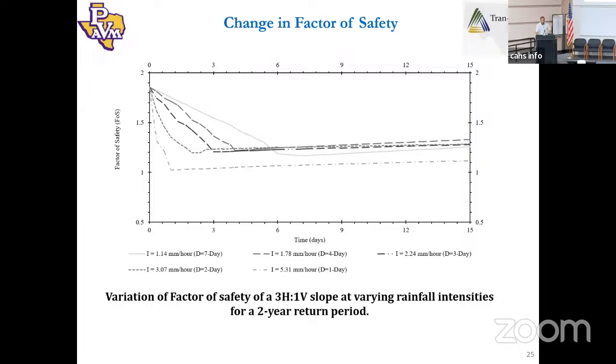But sometimes we have to make a steeper slope, and TxDOT is kind of forced to make steeper slopes to accommodate more frontage lanes, because based on the traffic study, they found that for this particular section, a lot of traffic has been added. So they have to add 1 or 2 additional lanes. So they cut the slope, make the slope steeper, and within the cutting zone, they add additional lanes, maybe 1 lane or 2 lanes. And as soon as you make the slope steeper, that makes your slope more vulnerable to failure. Okay.